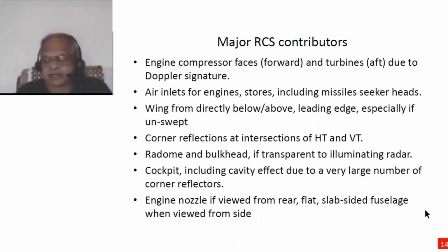Incidentally, it's possible to numerically estimate the radar cross section. It may not be an exact number, but it will give you differences when you make changes in the geometry. So incremental changes or incremental reductions in radar cross section can be estimated by numerical methods. Of course, this is not testable in a wind tunnel. You need a different setup if you want to do experimental testing.